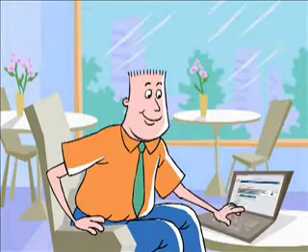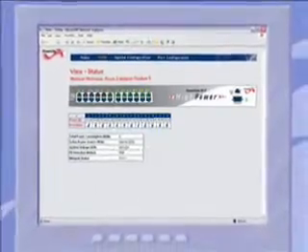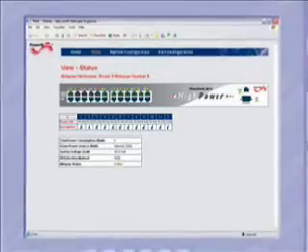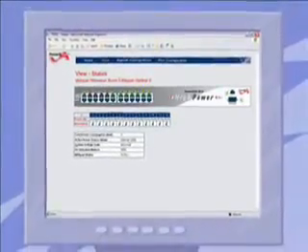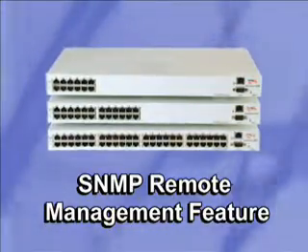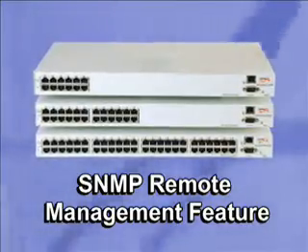And to make your life even easier, you can order a midspan with the optional SNMP. SNMP PoE Midspan's remote management option enables powering on-off individual ports, offering both web management and SNMP support. That means you'll be able to see the status of each device from any remote PC. All 19-inch midspans can be ordered with SNMPs, whether you need 6, 12, 24, or 48 ports.